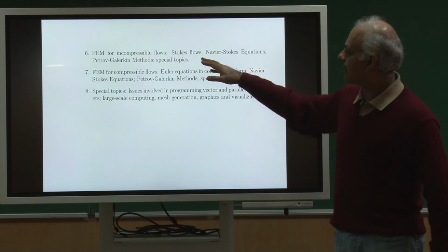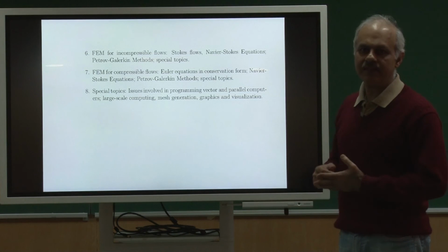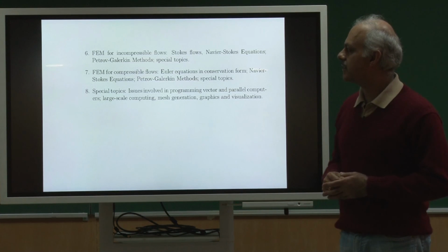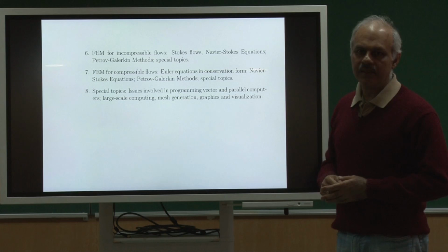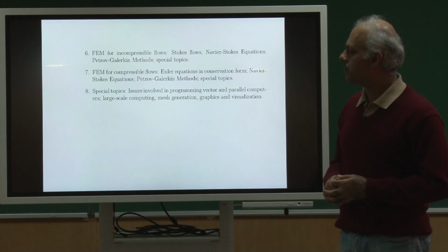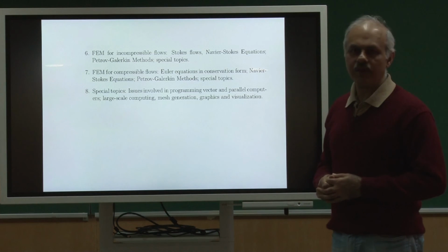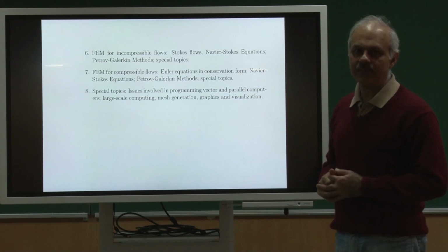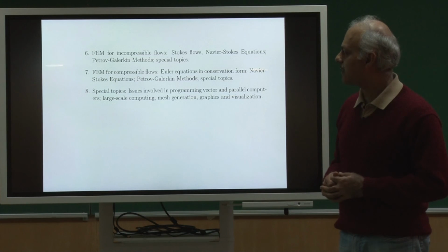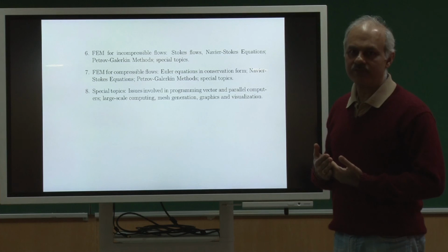Now these are extremely complex problems. If I compare a flow problem, let us say with incompressible equations, to a heat conduction problem, then the challenges are quite complex. As you are aware, the continuity equation makes a big challenge. In incompressible flows, the pressure term is one order lower than the viscous term, which actually is driven by the velocity.